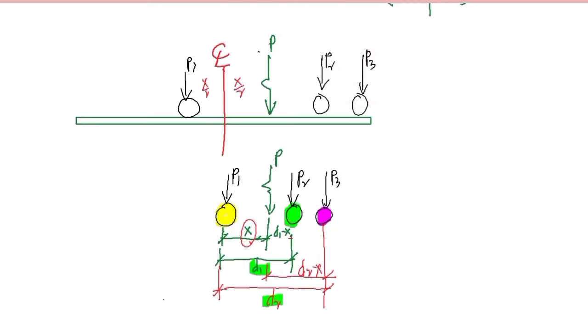So in this case, we will be taking moment at this point in order for us to compute for the moment created by P1, no? And kung yung left side ng beam yung pipiliin natin, what will create a moment here is the reaction at point A. So, mas madali siyang i-compute kasi isa lang yung kino-consider natin doon.